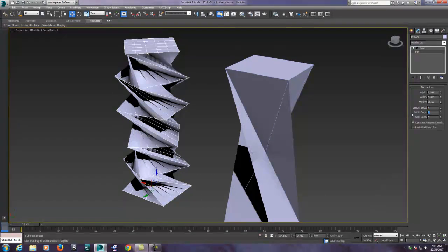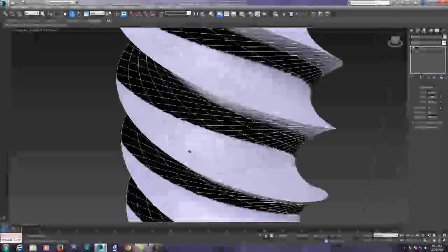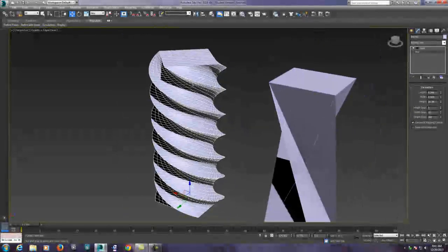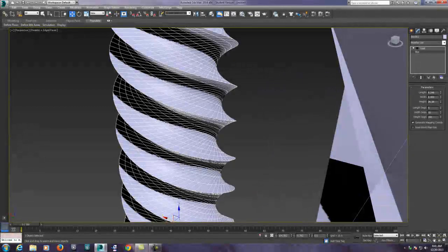And you'll see that once you get to a certain point, it's not affecting the model. Now here's where you're probably going to see a difference. You go to 10, that smooths it out a little bit, and then you go higher, and that's the one that's really going to improve. So if I go to 100 here, now my mesh is really nice and smooth again because there's a lot of segments in it trying to twist it.